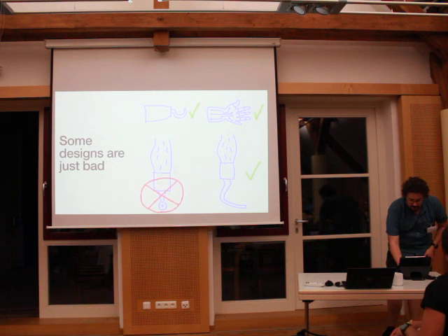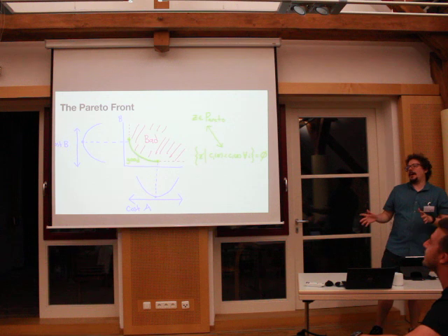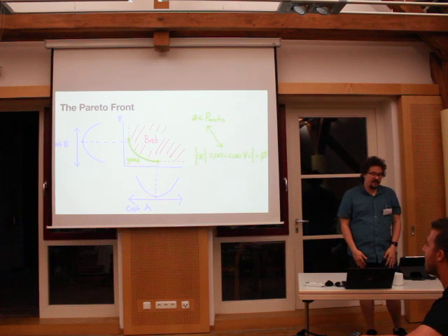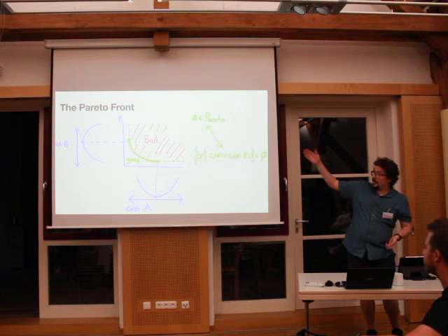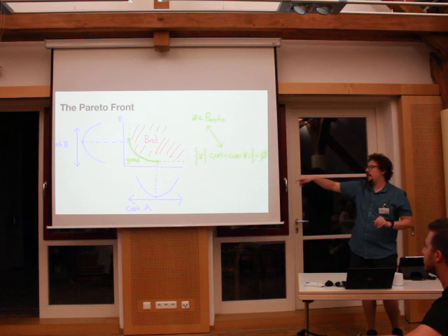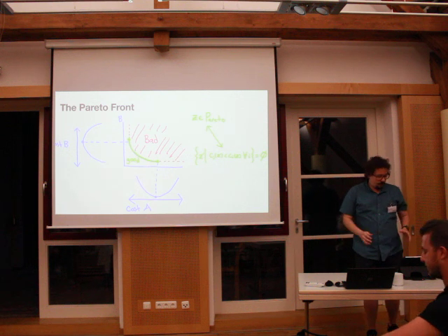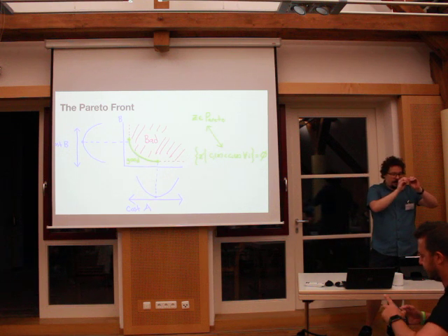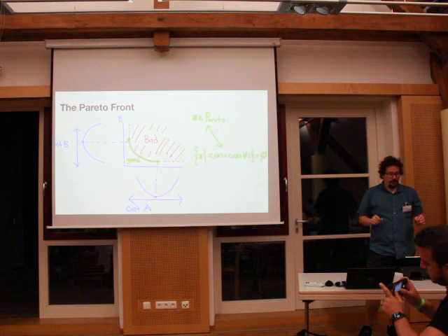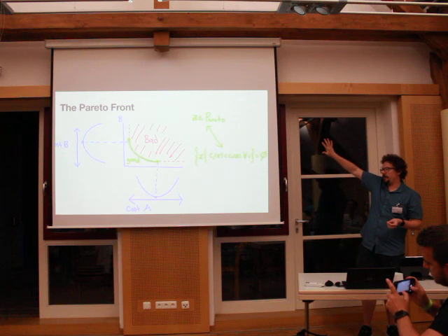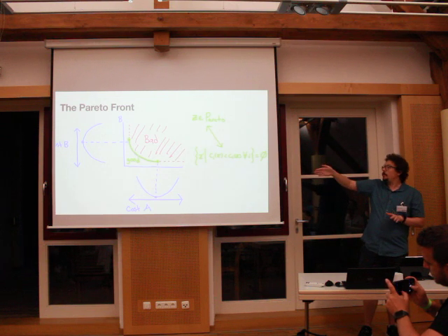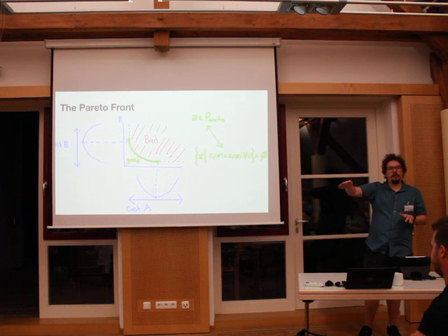But the challenge is how do we operationalize eliminating the bad designs and winding up with the good designs that we want to consider in more detail. To this end, multi-objective optimization can really help us in certain contexts. In multi-objective optimization, I maybe have multiple cost functions, like the one on the left, which is sideways, and the one on the bottom, and when you plot the costs for both of these in one Cartesian plane, you'll see that most of the designs which are up and to the right are bad. That's in red. But there's this nice green curve, and those are good designs.